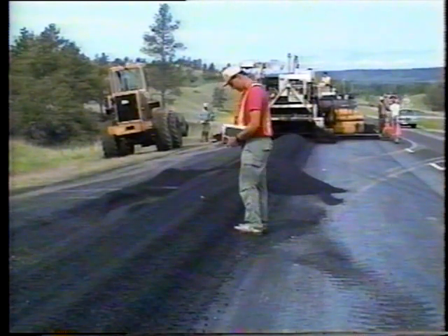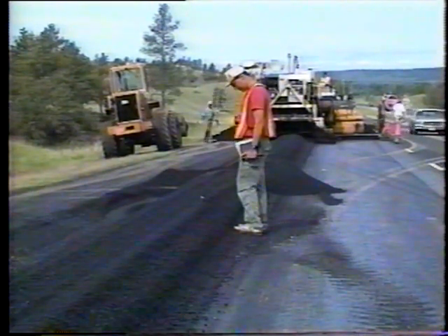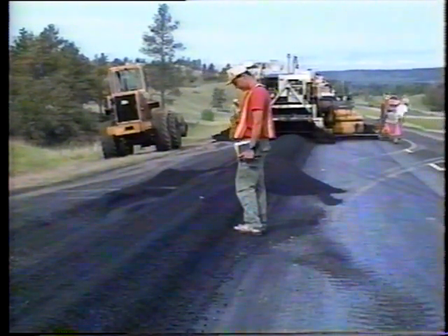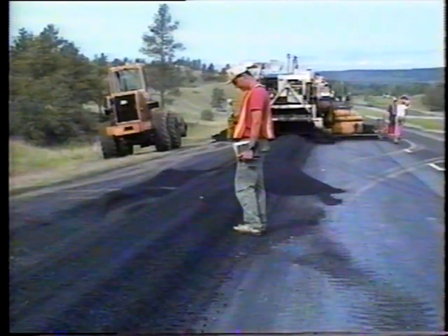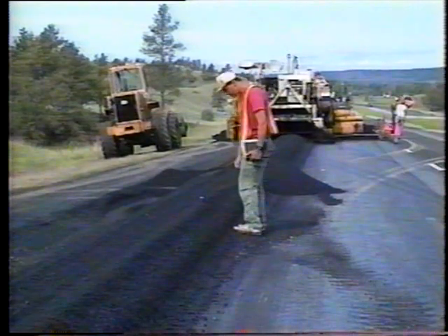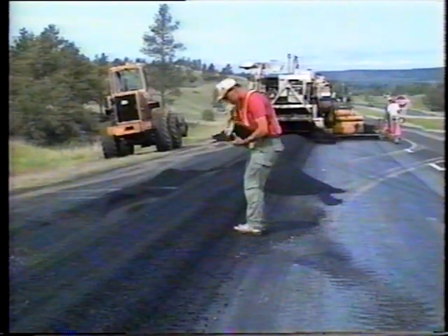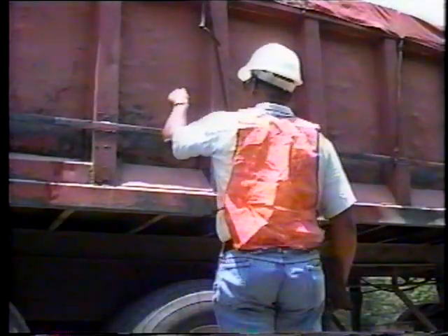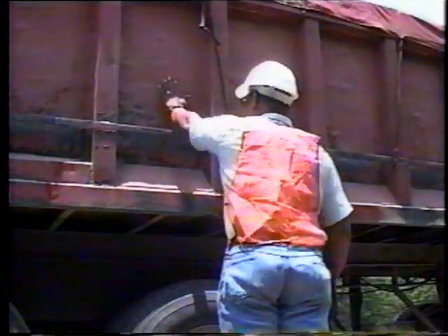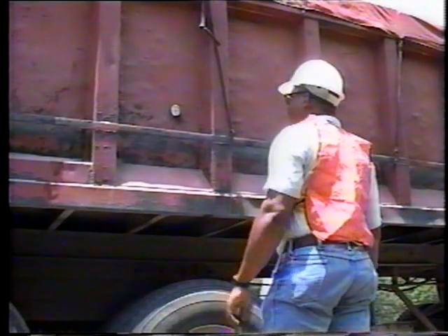Your first concern is with temperature. Too high a temperature can damage the asphalt binder in the mix. But if the mix is too cold, as you already know, the rollers won't be able to compact the mix adequately. The mix should be about 115 degrees Celsius when it's delivered, because best compaction is obtained when the rolling is completed before the mat temperature drops below 90 degrees Celsius.